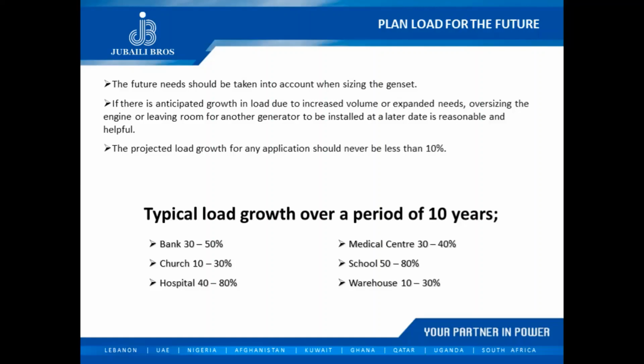For example, my actual connected load today is 100 kVA. I wouldn't go with a 100 kVA genset. I'd go, let's say, with a 135 or a 150, given that in the upcoming years, they might add some load. But again, I stress this: this decision is up to the client. It's a discussion between the vendor and the client, whether they want to account for future expansion or not.